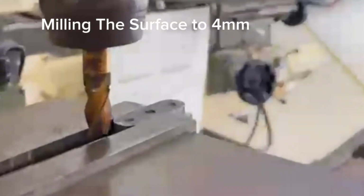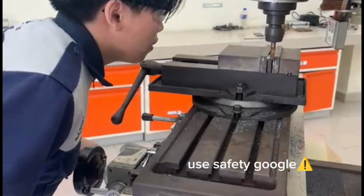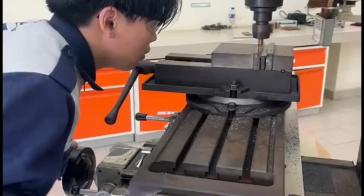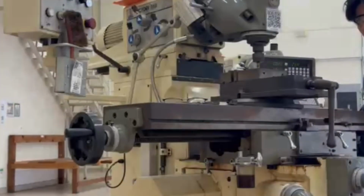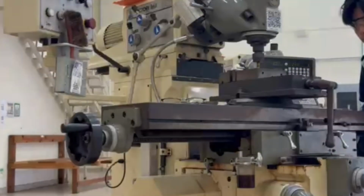The next step was face milling. We used the milling machine to machine the surface until it became 4 mm according to the drawing. Actually, while doing this step, there is a major problem, which is we can't mill the top of the metal directly. So, to solve this problem, we mill half of it first and then the other half.